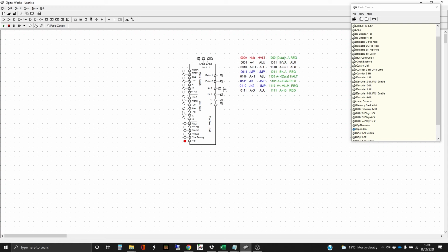And we need X1 and X2, and so we're going to check these. So X1 is halt. Yes. Sorry, X1 for 000 is halt. Going to check X2 for everything? I think maybe we need to. So 0001 is an ALU operation, and all we need for ALU operations is for it to ping the ALU, because the operation data is also going to the ALU. So let's do X1.